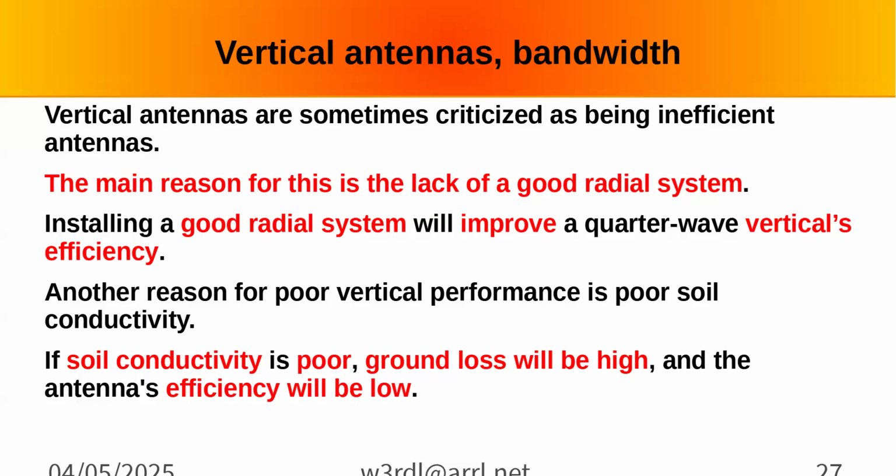So however many radials it took to do that big circle, it turns out that at 0.05 wavelength spacing at the ends, they're approximately a quarter wave long. But it wasn't because they were quarter wave, it's because they decided to make them 0.05 wavelengths apart. Why that? Some engineer picked it because it's a cost trade-off. I mean, you could put a solid copper plate down, but that would be kind of expensive. And for broadcast, we're talking long radials.